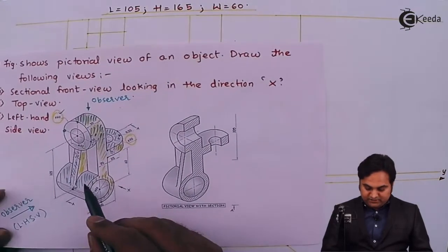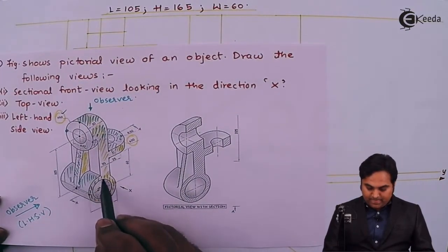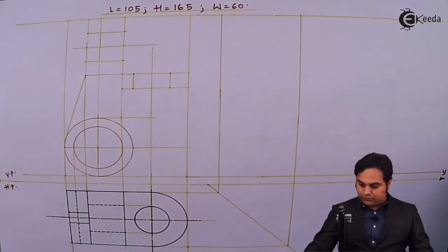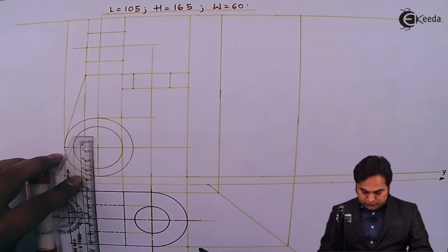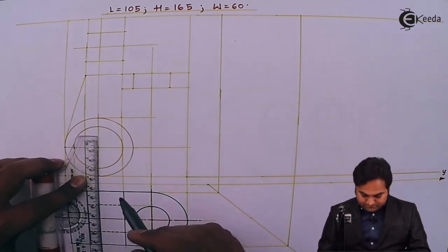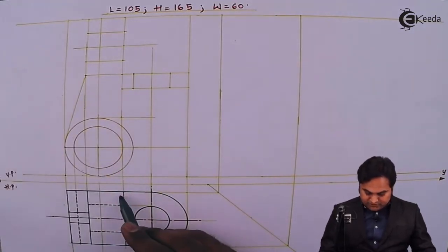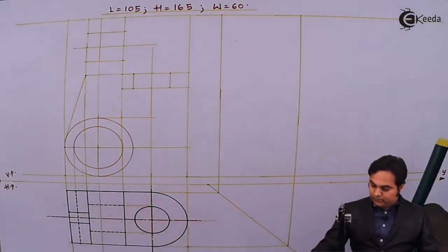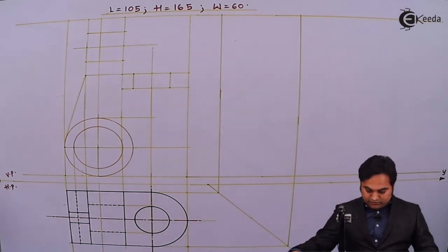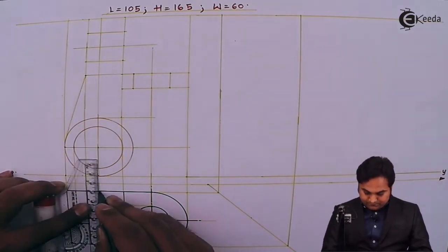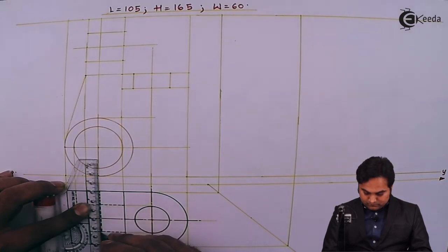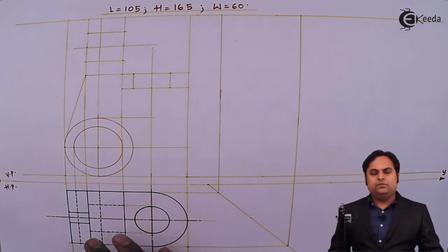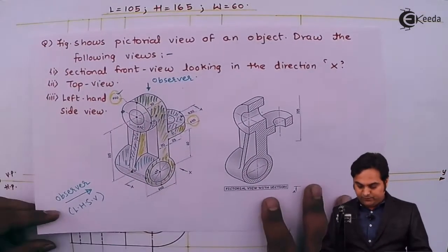After that, there is a cut inside this cylinder of 20 mm length, which I can get directly from the front view, and its width is throughout. So this is the cut. One side of it is coinciding with the dark line, no need to draw it, and this other side will be drawn having the width throughout as 60 mm. After I have reached here, I can say that the top view has been completed. Now going back to the side view.